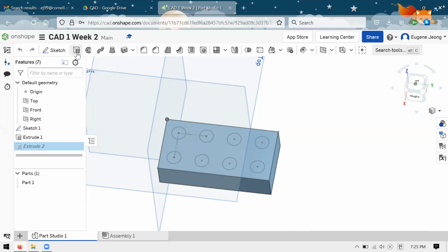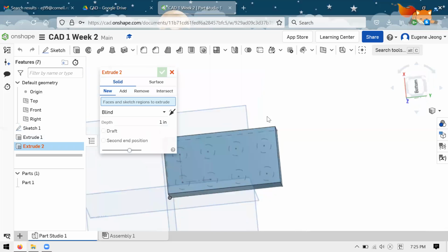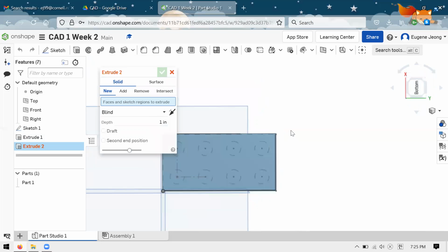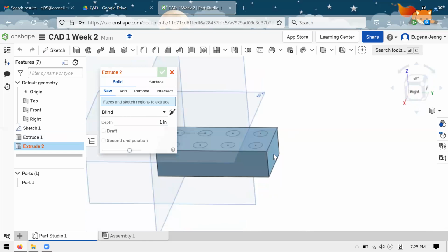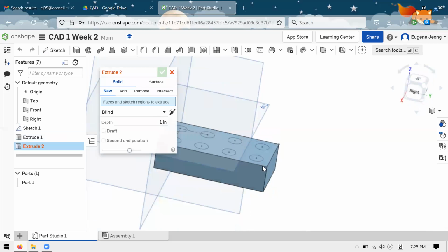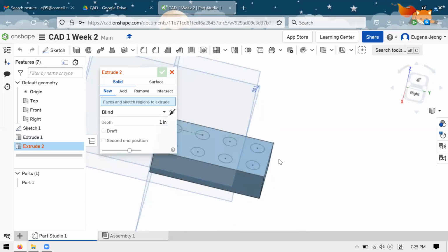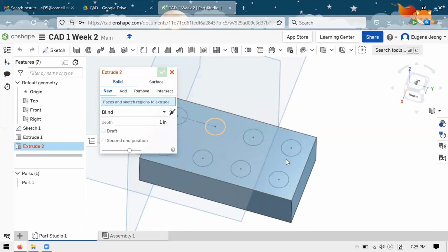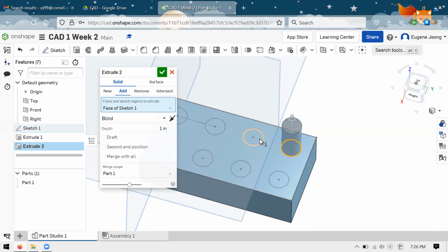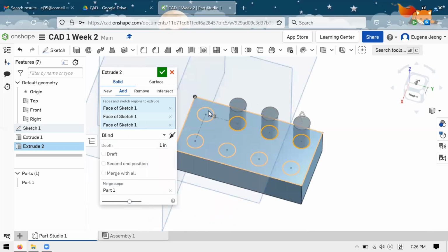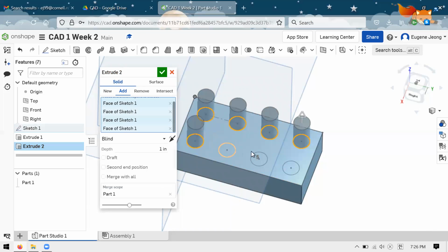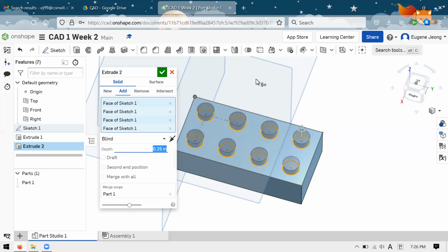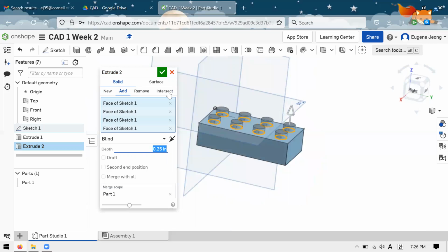You use the extrude tool again. Make sure you rotate to where you're looking on the sketch, not through to the sketch. Hopefully you can tell the difference. So I want this, not this. And with this extrude, I can actually just select these circles one by one, just clicking on them. And I'll set a distance, just arbitrarily a 1/4 inch. And that's how I made them.